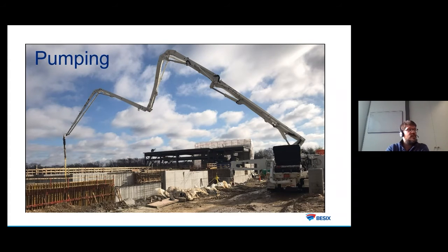And this is really important, because if you are using the wrong concrete in a pump, you will break your pump because the friction will be too high. And trust me, we have broken a few pumps already, and this is not something that you want to happen. So this is why it's really important to choose the concrete correctly, depending on whether it is pumpable or not. In this case, you can see the mobile pump. You can see the truck on the side, where the concrete mixers are coming and putting the concrete inside a pump, and it will go through all the pipes to go exactly to the place where you want.